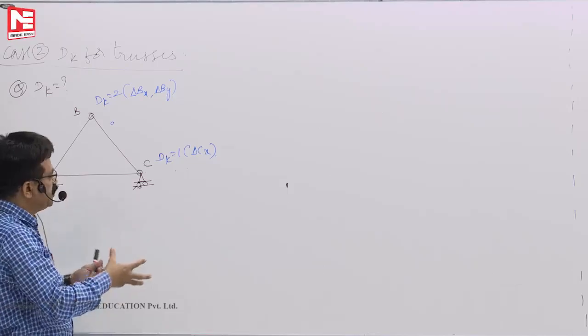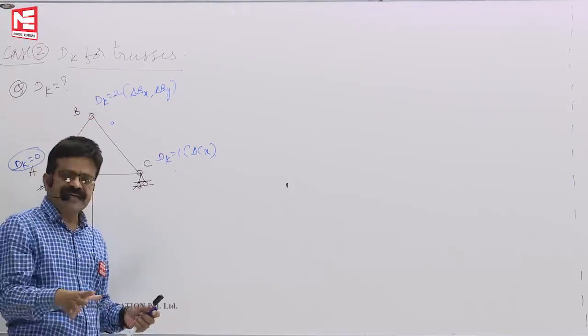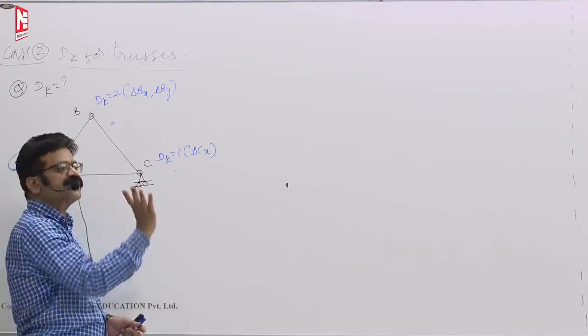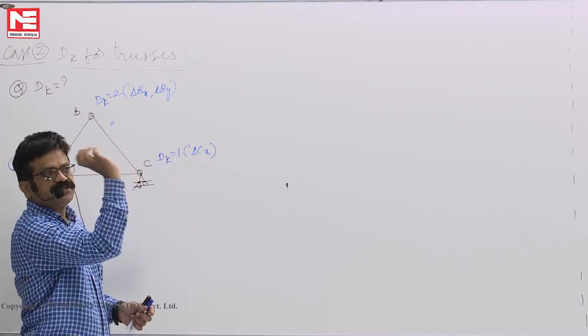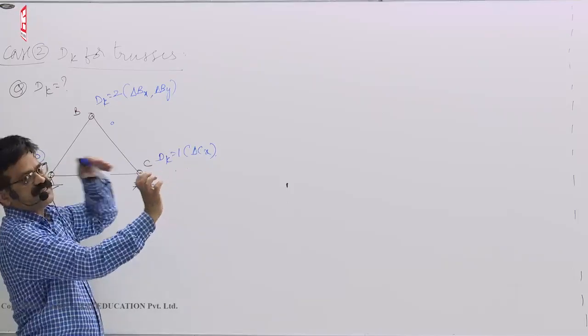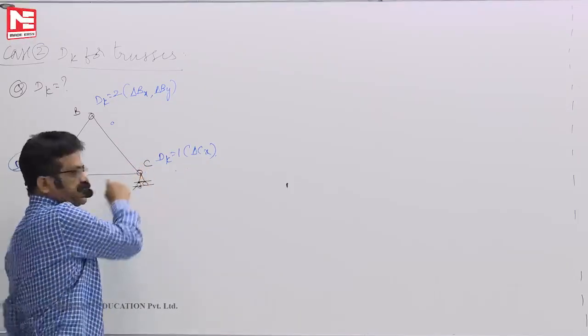You should not assume that the roller together will be lifted up. In any case, whether it is a guided roller support or this type of roller support, on this rigid plate there is a channel, so it will hold it. In a guided roller support, it simply translates, but in this case it will rotate also because of the bolt.